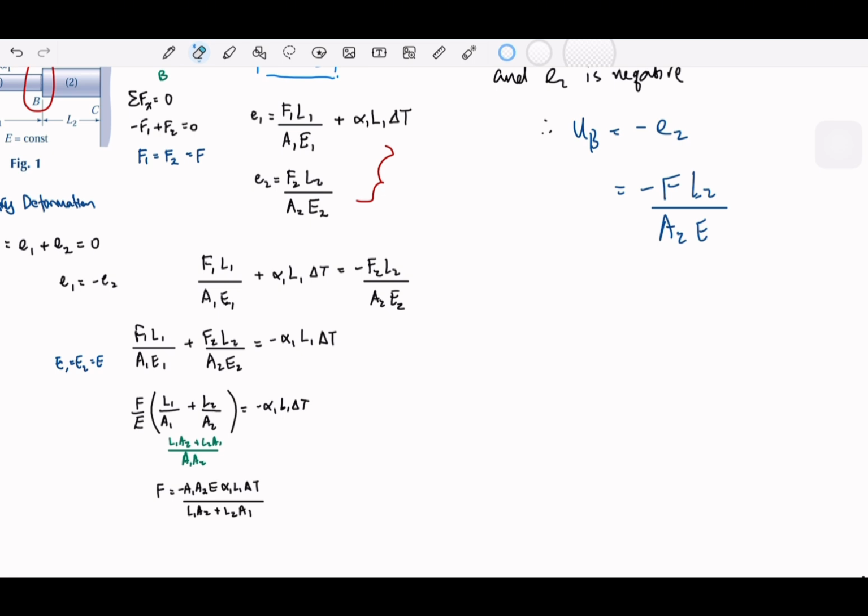I will go directly to the displacement method, which is very similar to the basic force method. The difference is that the basic force method observes the forces from each condition or each equilibrium, but in the displacement method we focus on the displacement instead of force. After we get the equilibrium of the displacement, we will get the deformation or force. I think it's better to give you some diagram and examples.